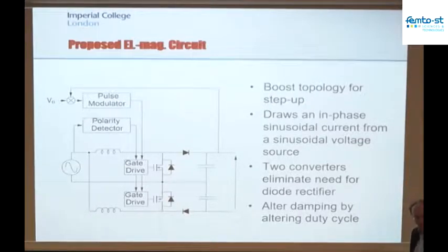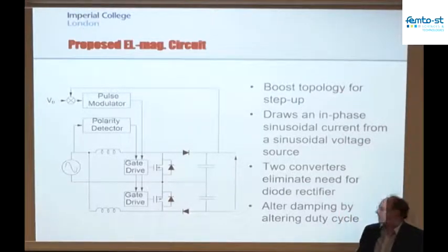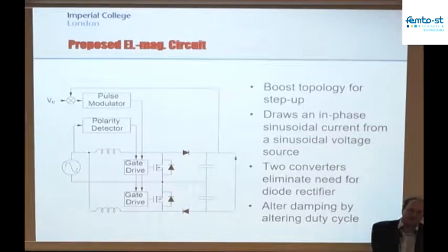There's an additional issue associated with this, which is how do you start the thing up in the first place? You need power to run the control circuitry, but when the thing is starting up from cold, there's probably no voltage on the output. So you probably have a passive startup scheme which bootstraps the active scheme.